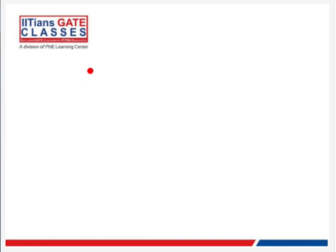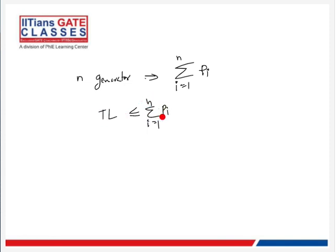Suppose you have n generators in the system. The total generating capacity would be sigma i equals 1 to n of Pi, right? Each generator will have its own maximum generation capacity, so this will be our total generation capacity. At any given point of time, our load will preferably, in an ideal condition, be less than or equal to this. If the total load is equal, then there is no confusion. You generate all generators at their maximum capacity. But if it is not, then we have to decide how much each generator has to generate.